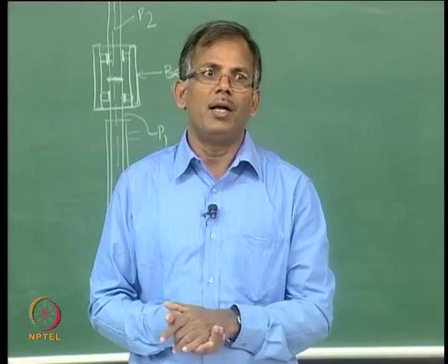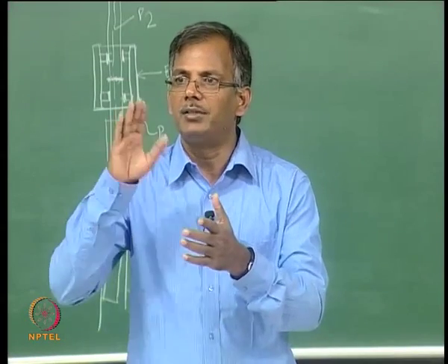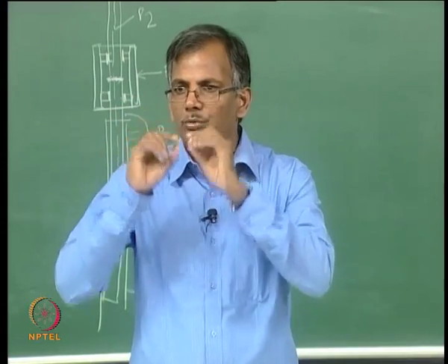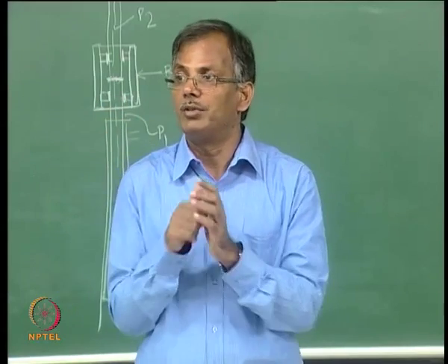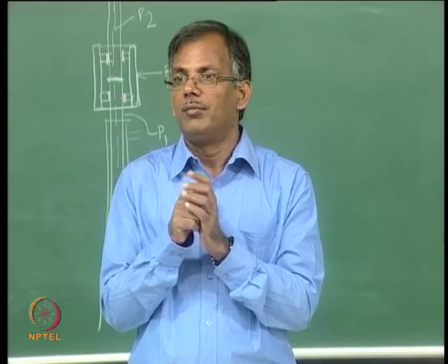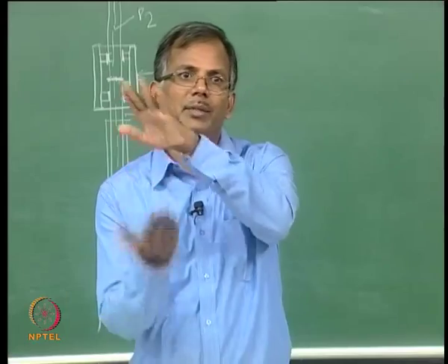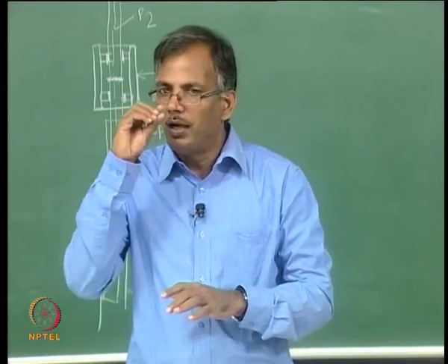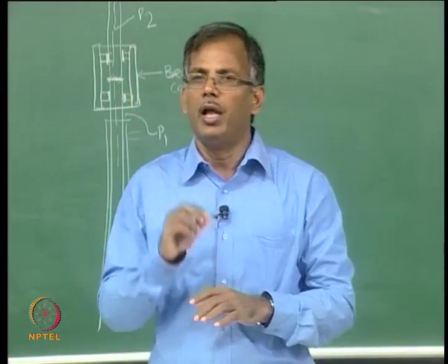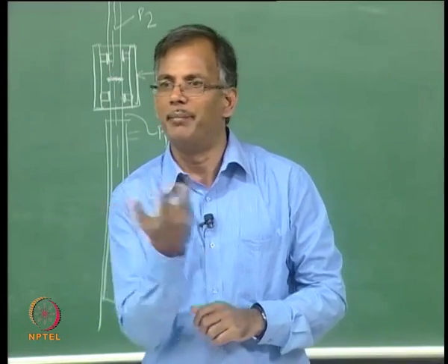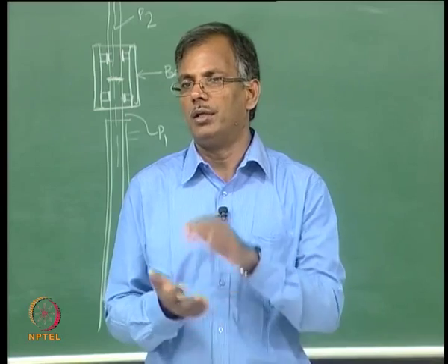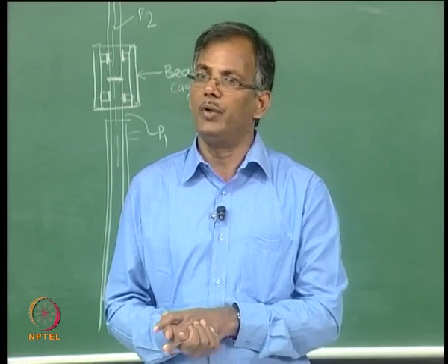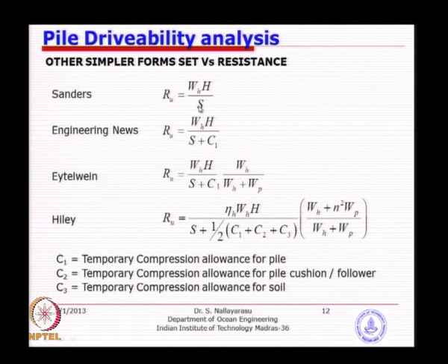Ultimately, for most of the piling onshore, we want to determine a criterion. I keep on driving, and when the penetration becomes too small, should I stop or should I still keep driving? The design is based on, say, 20 meters. You drive, but at the last 1 meter, if the penetration is very slow, every blow you are only getting say 1 mm, that means the soil is almost reaching, or at the depth of penetration at that location, the soil is very good.